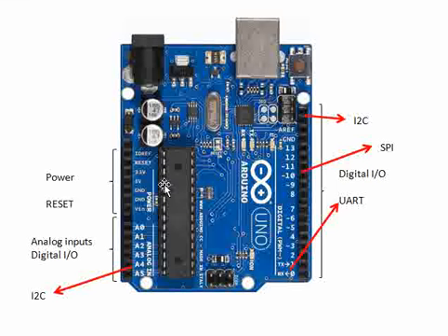So the first thing, this is a basic insight into the major serial and GPIO interfaces that are there on the Arduino board. If you see here, this top section is entirely power and reset signals, and the bottom section, even though it mentions analog, these pins can be used as digital IO as well. And then there is an I2C section over here. And on the right, all these pins can be used as digital IO.